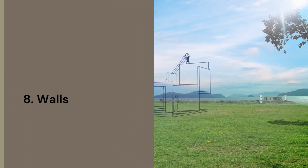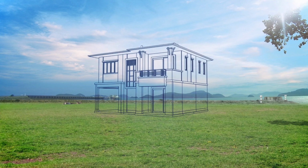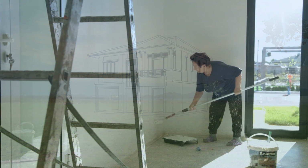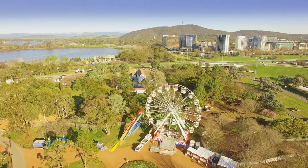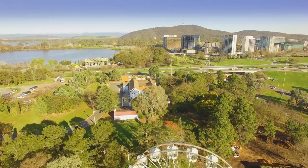8. Walls. In hot climates, the primary issues we focus to avoid are excess humidity or heat gain that could affect the building either immediately or in the future. Key design strategies: 1. Use white or light color external wall finishes to reflect the heat and in turn absorb lesser heat. 2. Provide ventilated claddings behind the external surfaces of the wall driven by stack effect to remove moisture in humid conditions.